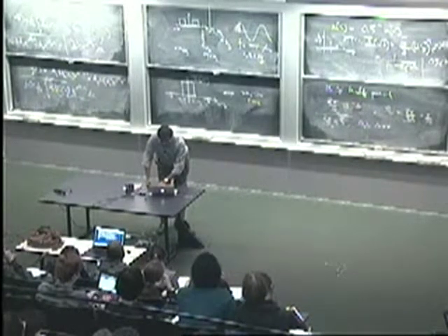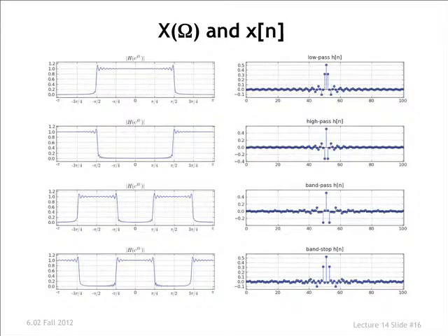So there is a signal that has flat spectral content. More examples of a similar type. And again, we first encountered these in the context of unit sample responses and frequency responses, but now I just want to change perspective and think in terms of time domain signals and their associated DTFTs. All right? So if we look at the top one there, this is the case we just saw, except I've truncated the sinc function. And so what I get is not the perfectly uniform distribution of frequencies in some interval. There's a little bit of a wiggle to it. But this is essentially the sinc function and its spectral content.